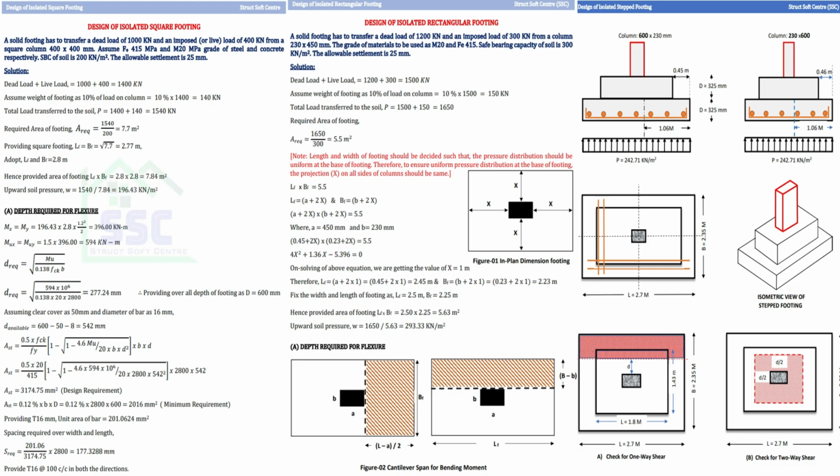If I just model the rectangular footing, apply the load, get the results and work with those results, it is just clerical work. It is not the actual way of learning and performing with the software. We should have knowledge about validating the results of the software. To validate the results, you should have knowledge about the manual design of the foundation, or any element, including the superstructure.